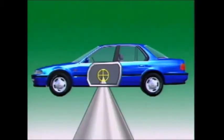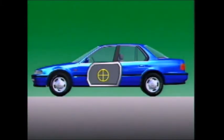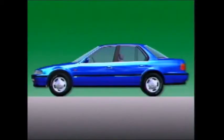The centre of gravity is the balance point of the entire vehicle. Its actual position depends on location of the major components. It is always located above the road surface and between the tyres. When a vehicle is cornering, this is the point through which all centrifugal force is assumed to act. Its position is determined by the load carried by the front and rear wheels. That is, by how weight is distributed.